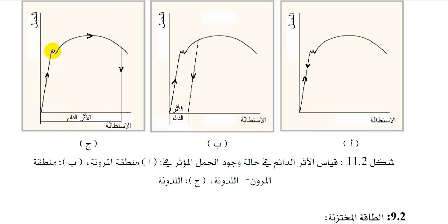After the limit of the point of elasticity, I just want to visualize this. After the point of elasticity comes the upper yield point and the lower yield point, then the necking will take place until reaching the ultimate tensile stress, the UTS point, plotted on the stress strain curve, by the action of the load imposed axially, up to the point of fracture, to finalize the effect of the load axially applied to the displacement.